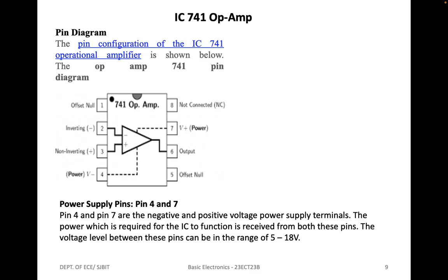An intermediate stage between the input and output stages is largely responsible for the op-amp's high voltage gain. Here it shows a BJT input stage while the other figure has a FET input stage. The op-amps that exclusively use BJTs are termed bipolar op-amps, and those that use a FET input stage with additional BJT stages are referred to as bi-FET op-amps.